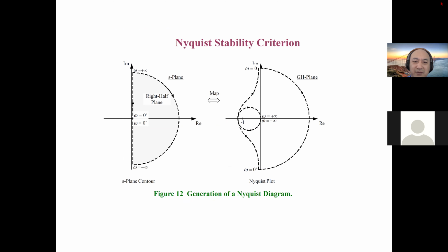So basically, Nyquist stability is about encirclement. If you encircle, then it is unstable. Basically, remember the eigenvalues, or the roots of the characteristic polynomial, in the right half plane. This is about the characteristic roots. So this is unstable, and that is mapped to Nyquist stability. That's why you have an encircling problem here. Okay.